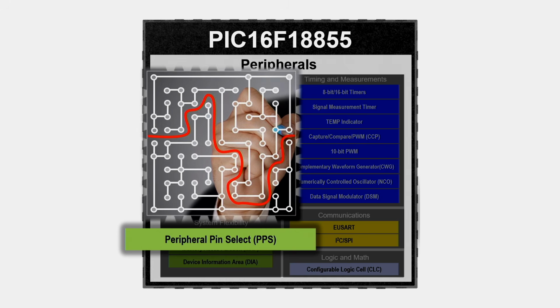So not much, yeah. I think another nice feature too is if you're routing signals around a new application, it minimizes the amount of tricky routing of the traces. Because as soon as you add a trace to a board, you're adding one of a few things. You're either adding a resistor, a capacitor, an inductor, or even an antenna, depending on certain situations. So the way you route your circuit on your board, the way you lay out your board, is really important sometimes. Yeah, of course.